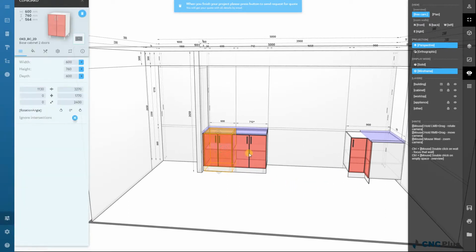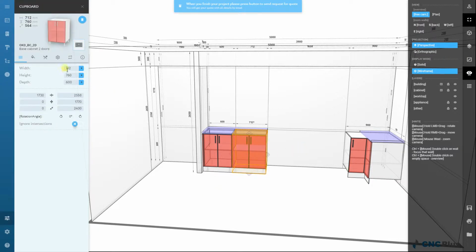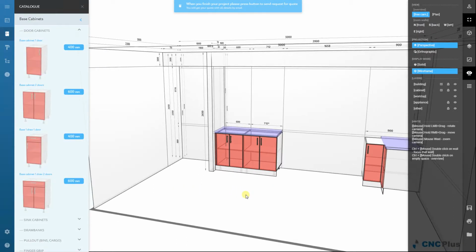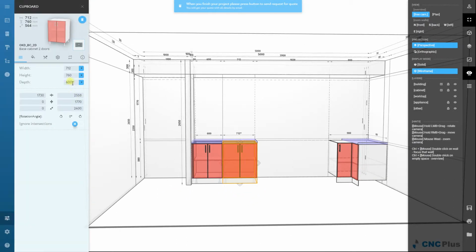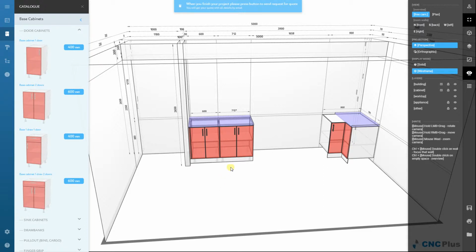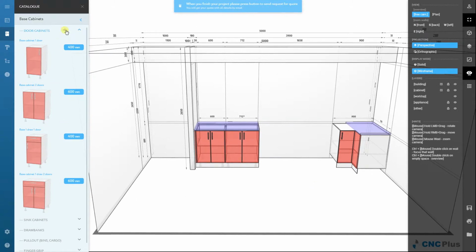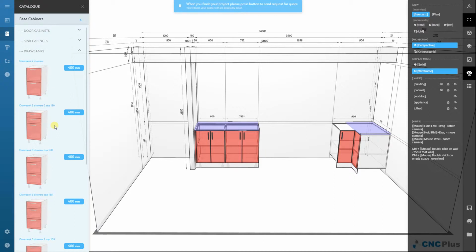So every size of every cabinet can be customized. You can change the width, height and depth. In the base cabinets, the depth of the cabinet is the depth of the bench top, actually the width of the bench top. We will allow for the frontal and back reveals, for doors and for technological installation reveals at the back.